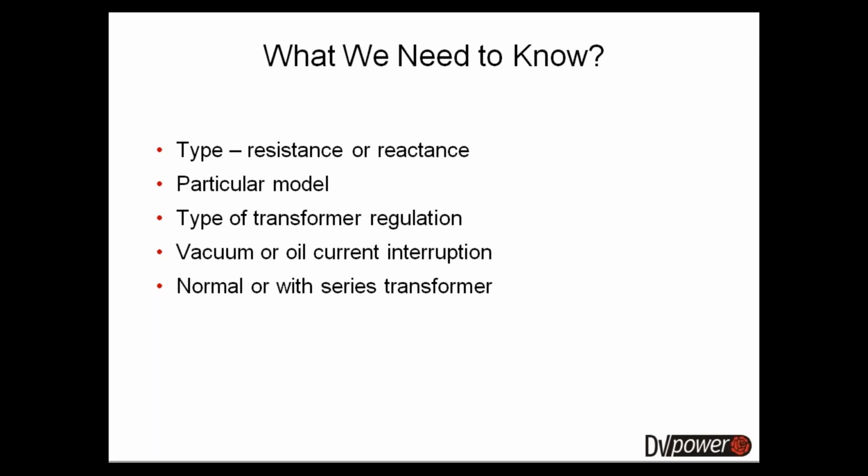They also need to know whether the current is interrupted by vacuum or by oil, and whether the tap changer is directly connected to the transformer winding, or if it is connected through a series transformer. And this is something that I will explain in more detail later on.